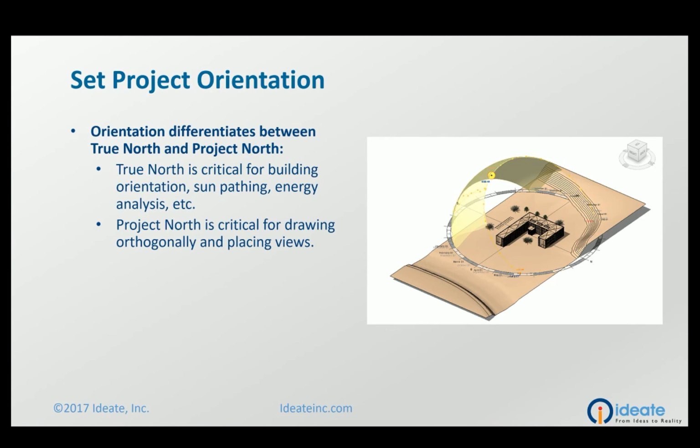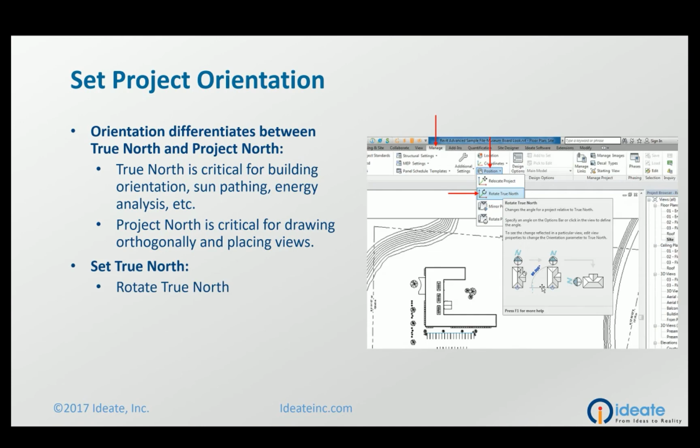And with that, if you get all that coordinated, this stuff should come naturally, right? And of course, when you're looking at doing presentation drawings or renderings or any sort of energy analysis, you have to make sure you set your project north and True North, right? And it's really more about True North than project north. But again, the whole idea behind project north and True North is getting your project oriented and then, of course, getting your drawings oriented as well. And of course, you can rotate True North. I think we've all done that, and we've probably all messed it up at one point in time.